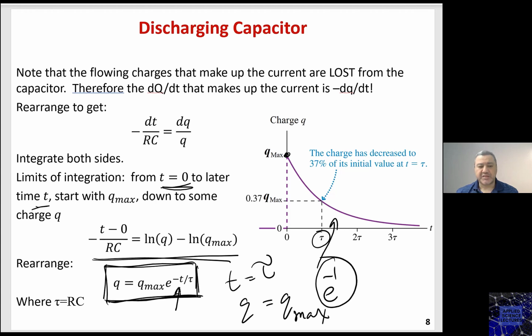So this represents the value after tau. Now always keep in mind that this is going to give you a value that is shifted 0.37 or 37% away from the final destination. So if my final destination here is 0, then a shift of 37% means this point,